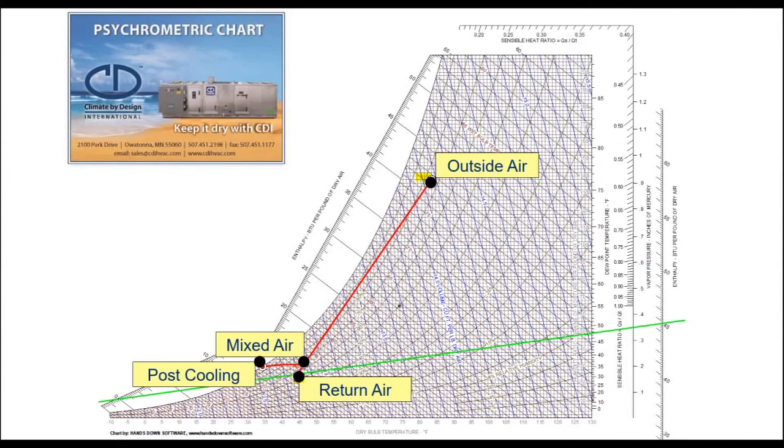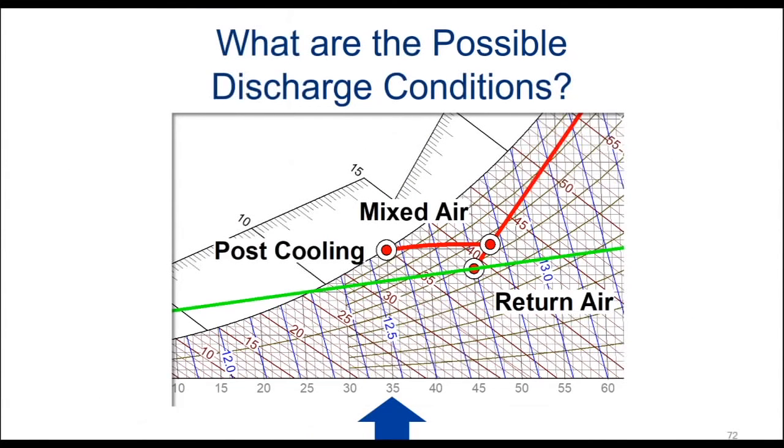We're going to drill into this just a little bit closer. We were given an ammonia system that we could come off of a coil at 35 degrees. That's as cool as we could get with that available system. So at 35 degrees, we were to control this room. However, when we put the sensible to total heat ratio line on here, you can see that we are not getting to the line. Or let me state it differently.